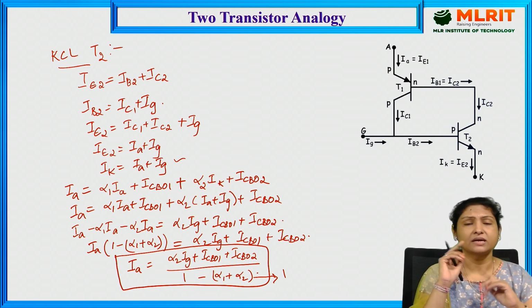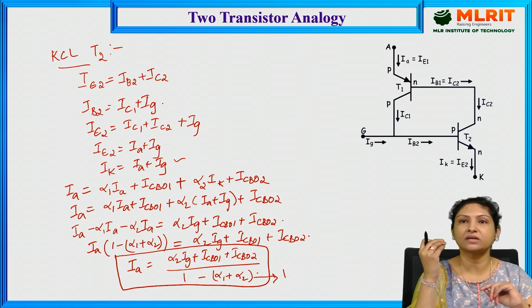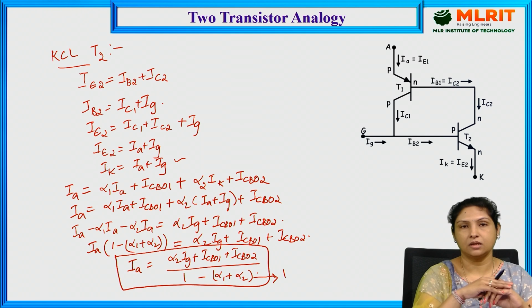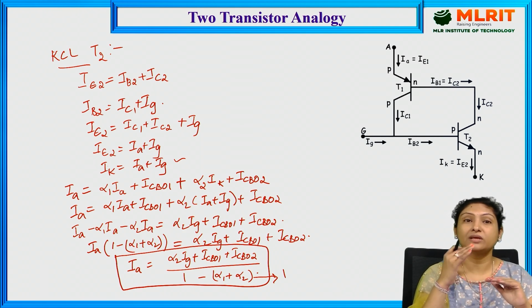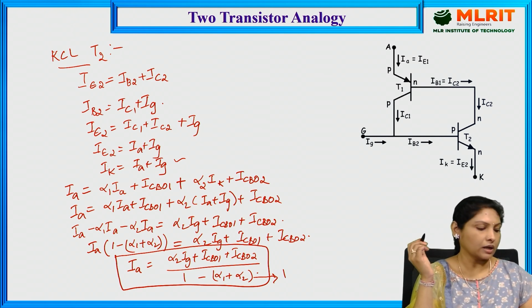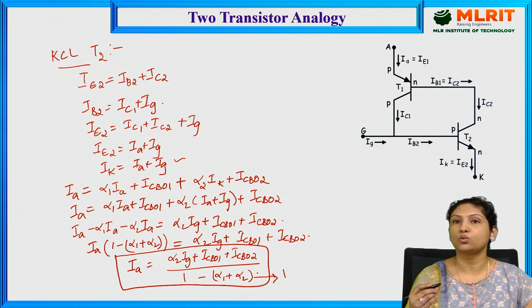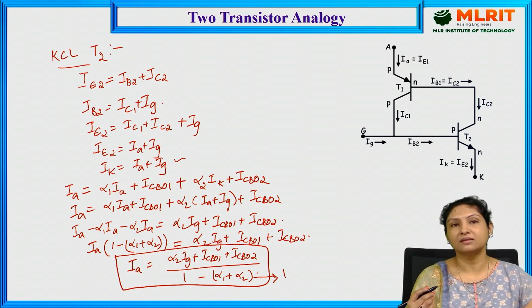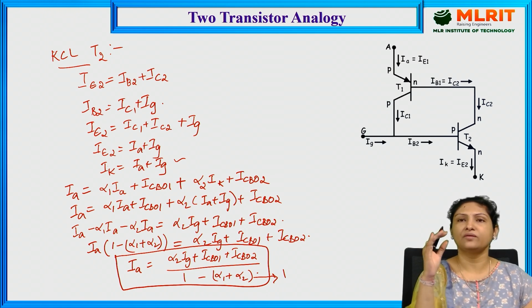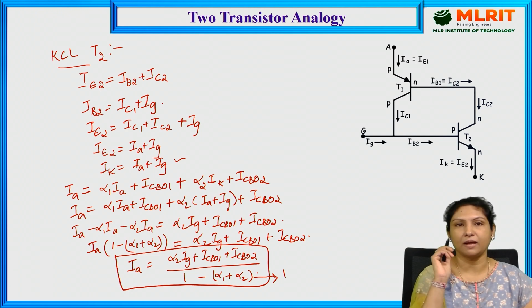Whereas for a transistor, we just have to provide the continuous base signal such that it remains in the on state. Coming back to the thyristor, we bring it into the off state by providing a negative voltage from anode to cathode. Whereas for the transistor, if we just withdraw the base pulse, the transistor will be off. So this is the basic operational difference between the thyristor and transistor.